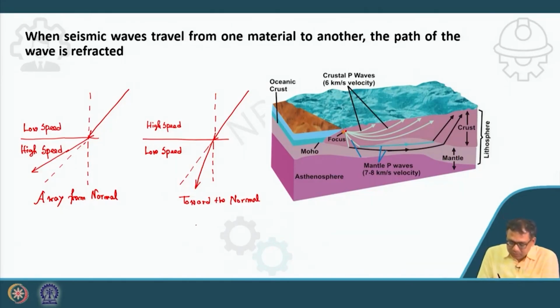If I write down the shear wave velocity, it is root over G by rho, that is, shear modulus divided by density. Now I am saying velocity increases as density increases, but the formula does not seem to show this, because velocity is proportional to 1 by root rho. But the reason is that when density increases, the modulus value will also increase.